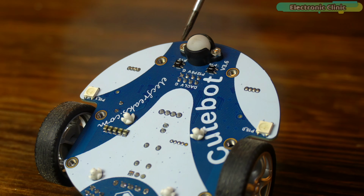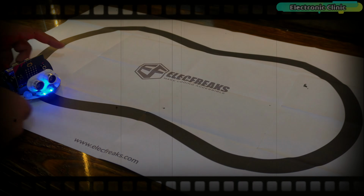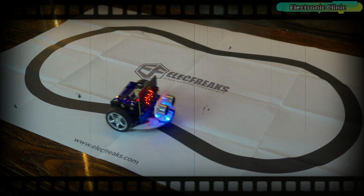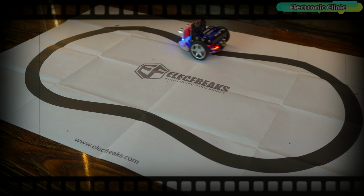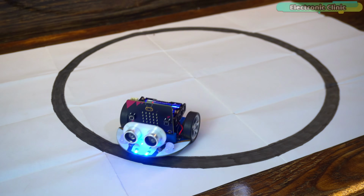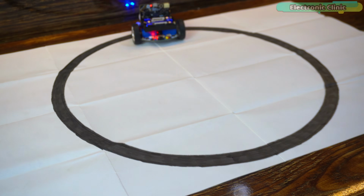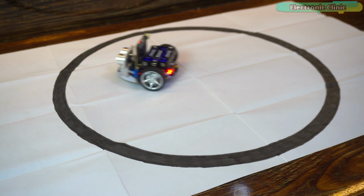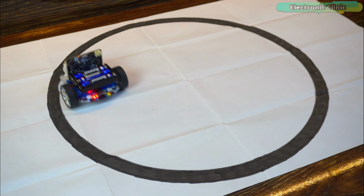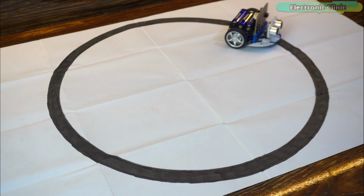This robot has two IR sensors on its bottom side which help us easily detect white and black colors. In a previous video, I programmed this robot in such a way that it would only follow the black line, turning it into a line follower robot. Anyway, when both IR sensors detect the line at the same time, the robot moves backward and then tries a different direction. And if one IR sensor detects the line, the robot turns left or right.